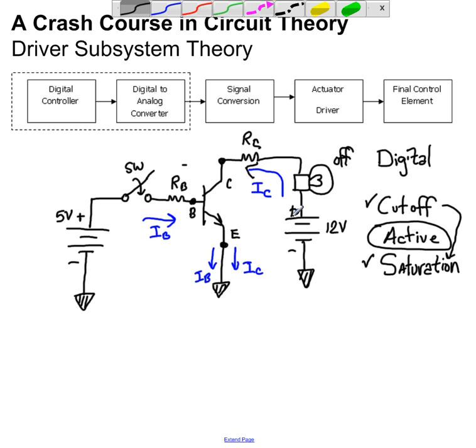So now the current can freely flow out of the battery of the 12 volts into the transistor. Of course, in the emitter, the current from the collector and the current from the base will add up. But typically, the current from the collector would be much, much larger than the current in the base, sometimes on the order of 10 to 100 to even 1,000.